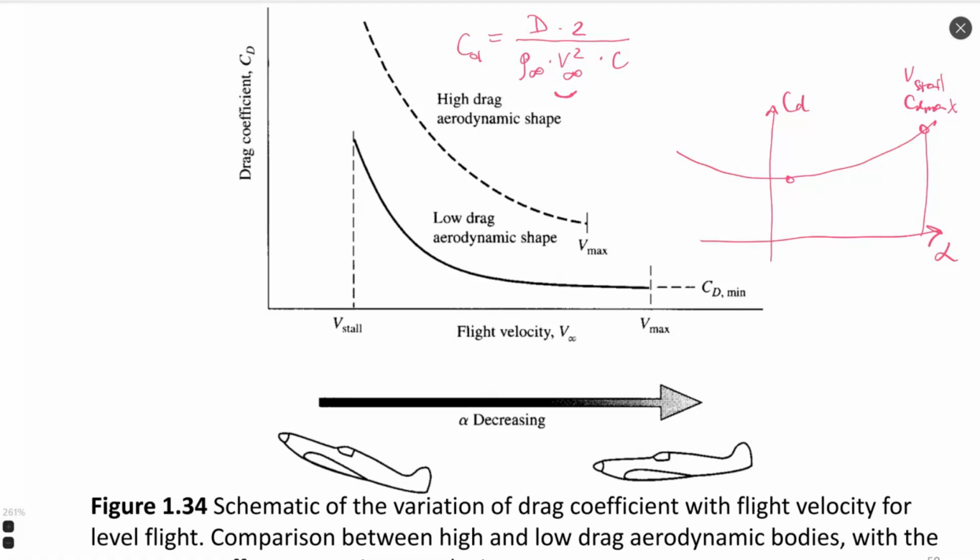If we have an engine with constant thrust or maximum thrust that we cannot change, that value of D becomes independent of the angle of attack and just enters this equation as a constant. So nothing depends on the drag value. Here only velocity and the value of drag coefficient are important to determine their dependence on each other.